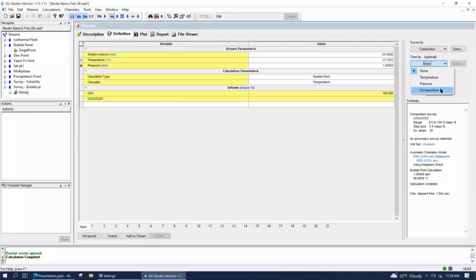Everything that we've done at this point is that we just calculated the final state of the system. We did no mixing or anything. We just said, these are the settings at the final state. Tell me what is required: how much material, what the final temperature is. But when we go to chapter 5, we're changing that whole idea. We're saying, I've got material A and material B at their initial states. I want to mix them together to make a combined material. What are the changes when I go from this side of the mixer to this side of the mixer? How much heat's released, how much solids form, if a vapor forms, etc.